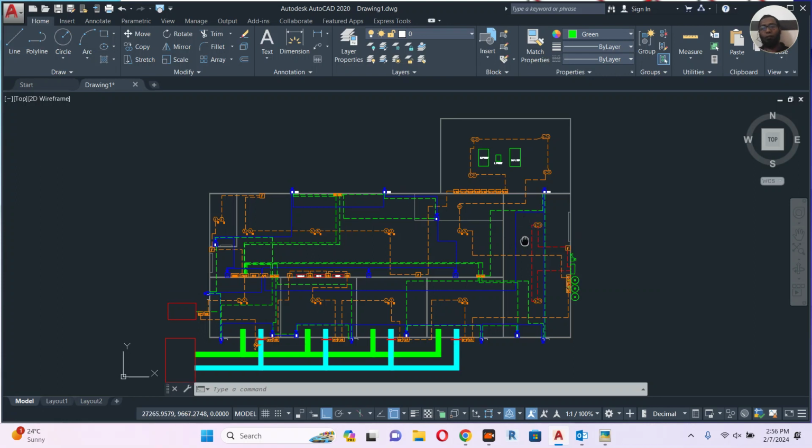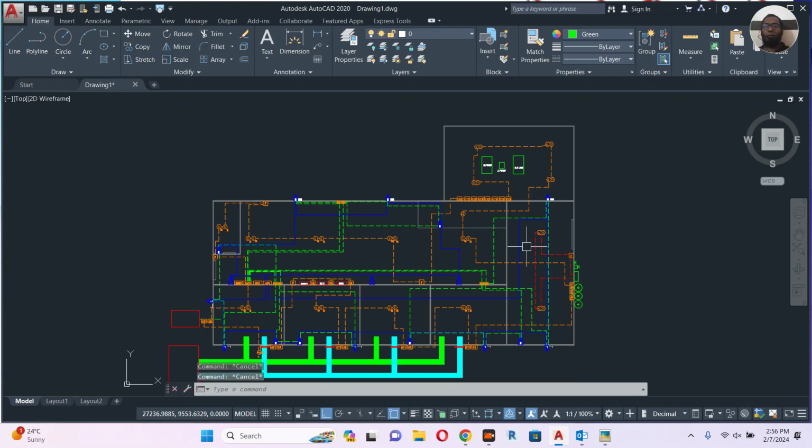The fire system, if you have some other building specialized panel, if they request some modules or control relay, you have to provide it in the fire alarm. It will keep changing every time. One time what happened, for every motorized damper we provided one control relay and monitor module. Let's say we have 10. We provided 10 monitor modules, 10 control relays.